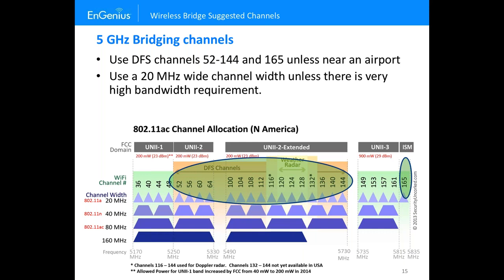If you're really nearby another radio, it could trigger that. If you mount, say, two bridges on the same pole and they're only a couple inches apart, that's too close to each other, even if they're entirely in different bands. Like you've got one on channel 165, another one on channel 36. Even if you're hundreds of megahertz apart, it's still so close that it gets misinterpreted. The interference gets triggered as a false DFS event. Weird stuff happens when you don't follow best practices.